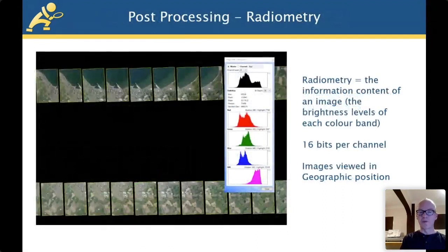At the same time, we've got a load of images, and we perform radiometric corrections, which is basically color corrections. You're capturing over a 3 or 4 hour time period. The lighting conditions may change. The brightness and darkness of the features on the ground may change. There are a lot of really clever algorithms which account for things like the angle of the sun at the point of every capture. So all these little brightness variations can be accounted for, a lot of it by automated algorithms.